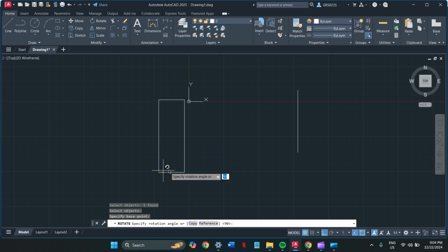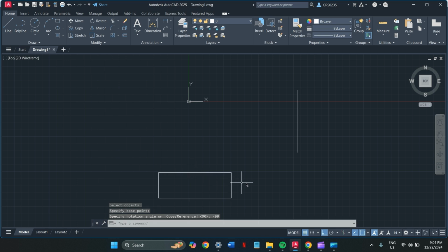it. Then now we can just drag it for its rotation, or we can type out the number or the angle for the rotation. So a positive number goes counterclockwise while a negative number goes clockwise. So let's test that out with typing negative 90, and that will in turn go to a clockwise direction.